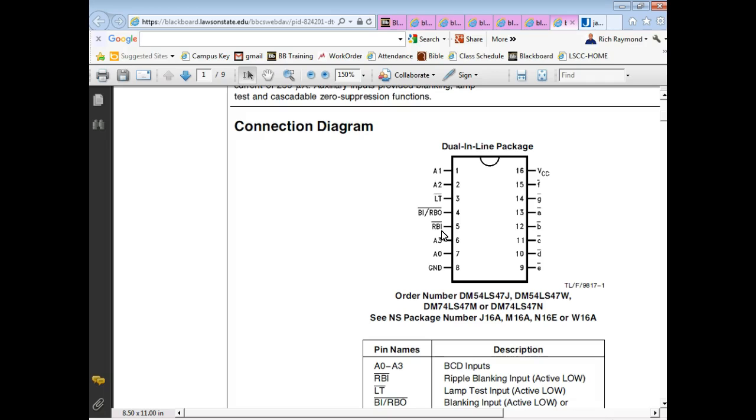It has 5 displays on it, and it's using a 7447 to decode it, right? That would mean 4 inputs for every display. But when you look in there, there's not. There's 4 inputs being shared by all of them. What they do is they multiplex. They allow multiple signals to share the same line.